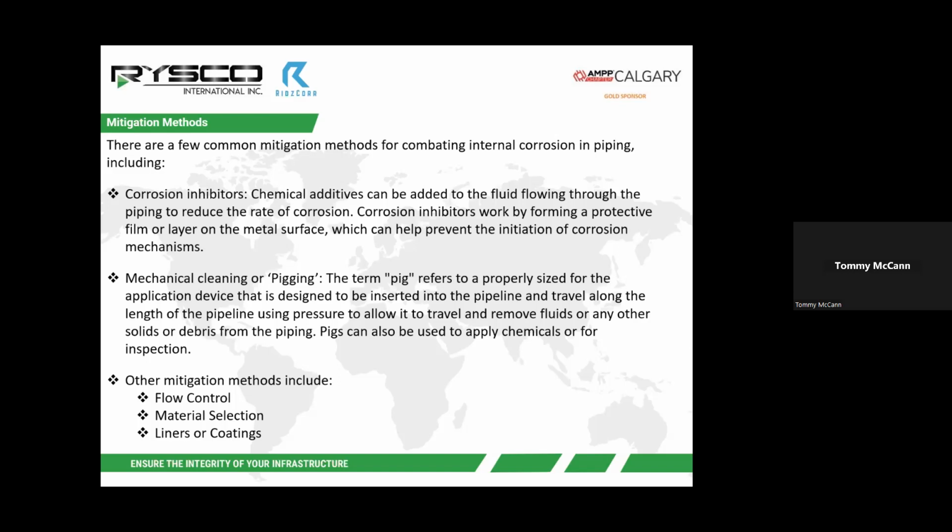Second most common would be what's the industry term of pigging or mechanical cleaning. So where you have a device that's sized for the system in use, and you insert it into your piping or pipeline, and it travels along the distance of the pipe. It's back pressured behind it, and it pushes in front of it out into a trap fluids and solids or debris, trying to rid those influencers from your system.